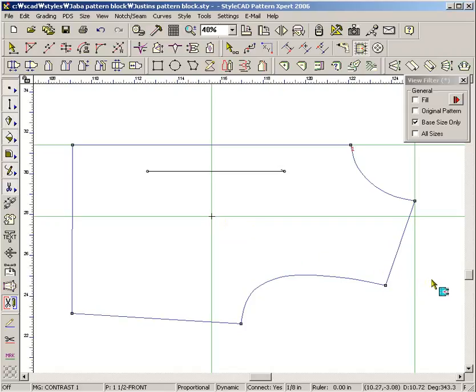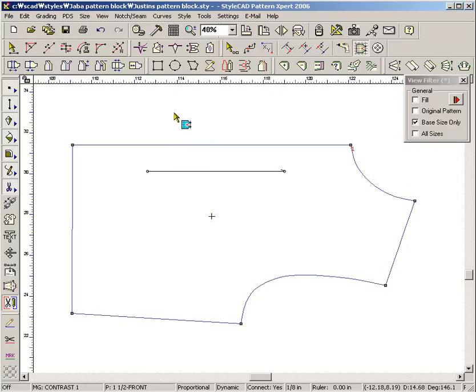In order to delete guidelines, select them with the Ctrl plus Tab keys and press the Delete key. The Two-point guideline tool creates a guideline that goes through 2 points. Press the Ctrl key and left-click the ruler area. Then, drag from point A to point B to make a guideline connecting the 2 points. In order to move a guideline, select the guideline, enter the distance, and drag it.